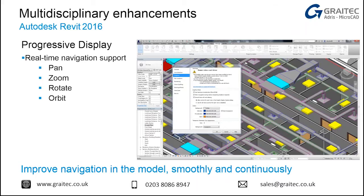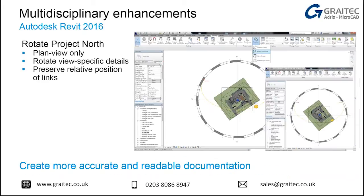Okay, so some of the new features, particularly from the platform, have all been about performance this year. It's about enhancing the speed and how we can use Revit. Progressive display gives us better support. When we're moving our models around, if your computer's graphics card isn't quite up to the job, it will just degrade the scene while you move around. Once it's finished, it will then redraw. The other advantage is it will allow us to navigate whilst it's redrawing things. If you've made a big change to the model and it's having to redraw a lot of information, whilst it's doing that, you can still pan, zoom, rotate, and orbit within that view as well.